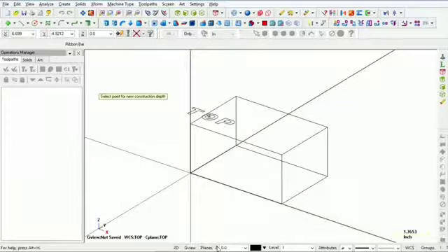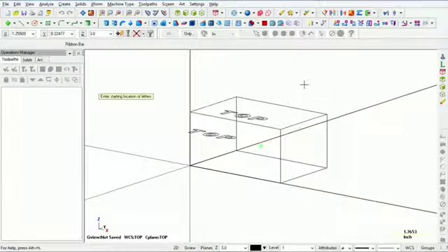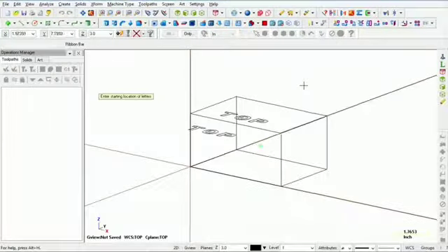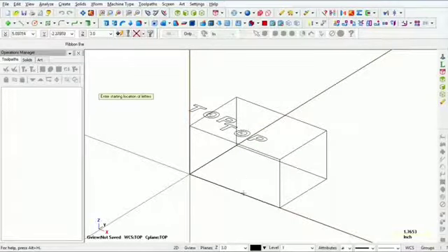So if you left click on Z and you snap to that top portion right here of the box, notice how it puts in 3 inches. So now, if I locate my cursor right here in the middle of the top of the box and click it again, now you can see the top is located right on top of that box. And so everything that you draw at this point is going to be drawn on this 3-inch plane up from the bottom of the box.